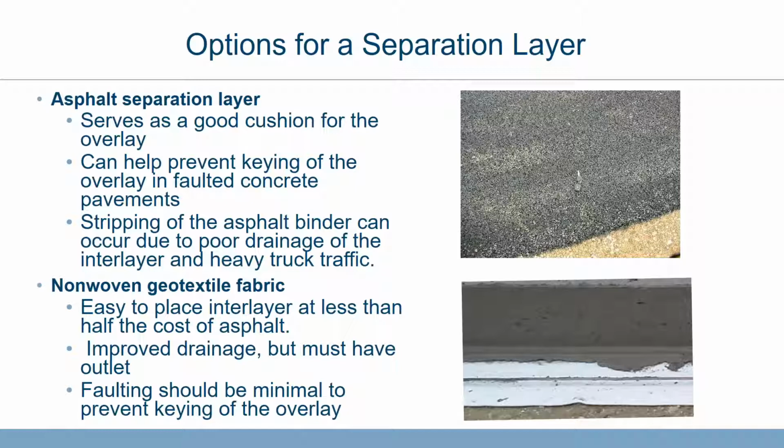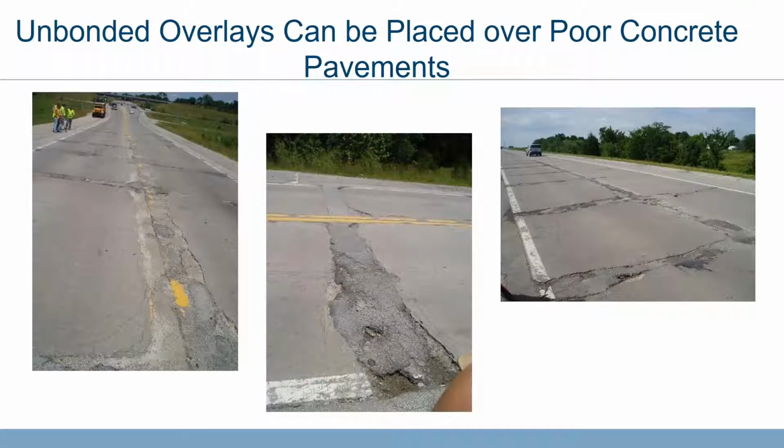Peter showed last week the asphalt separation layer that we often have seen in the past as a stress relief course, as a bond breaker. Today we see more and more utilization of the non-woven geotextile fabrics, because they do add some value to the project for the contractor in being able to have a control of that operation and get that done in a timely manner.